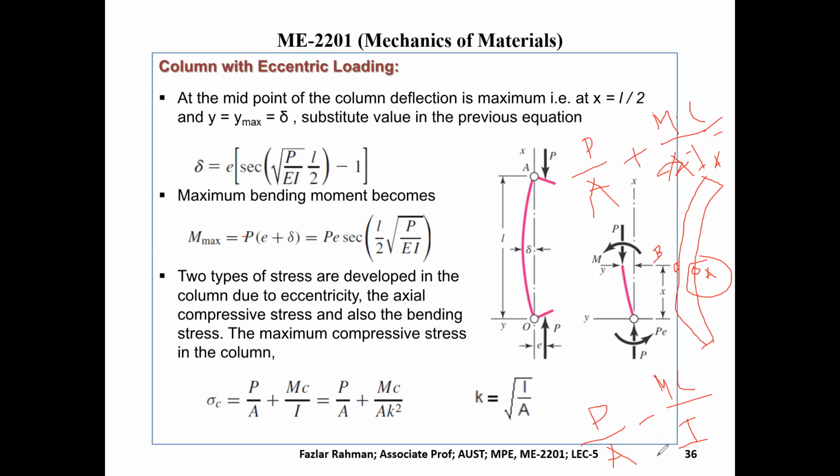Okay, so sir, that's why they took only the absolute value of the bending moment, because this absolute value of the bending moment is making the column compressed on one side and compressed on the other side as well. And that's why it is more critical. In the aerospace and shipbuilding industry, when we attach a column at the end, you need to make sure that there is no eccentricity in the column.